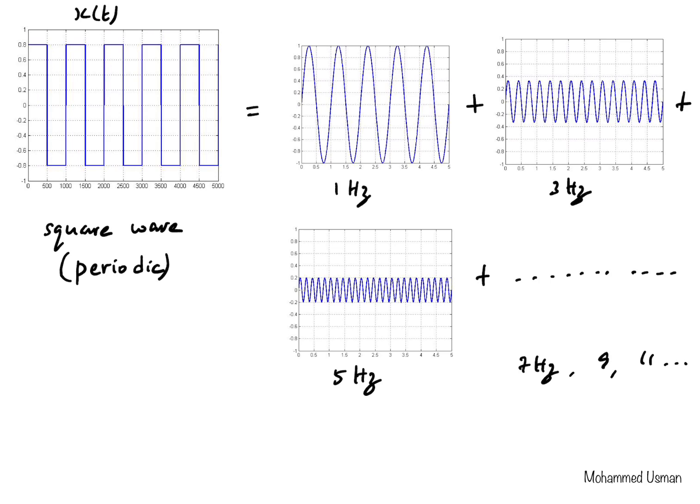The process of converting this time domain representation into finding these frequency components is done by the mathematical process of Fourier series or Fourier transform, and because it's periodic, it is Fourier series. If you notice here, the 1 hertz component has a specific amplitude which is 1 volt.